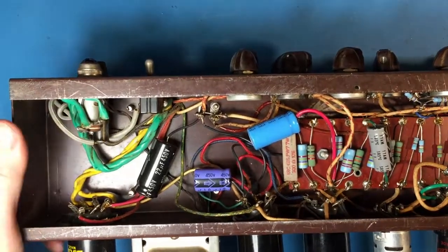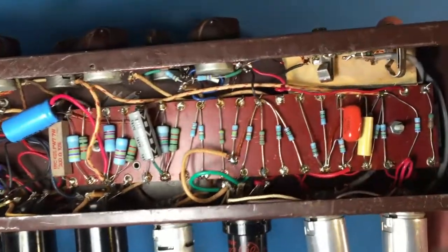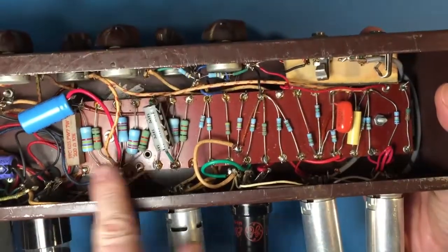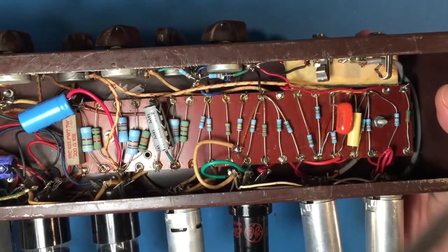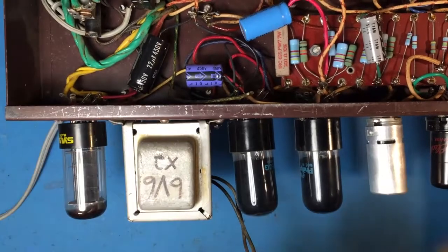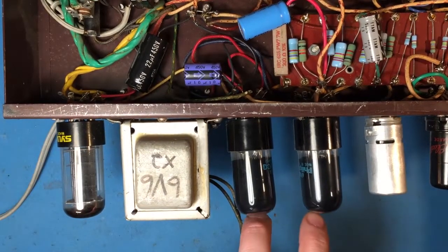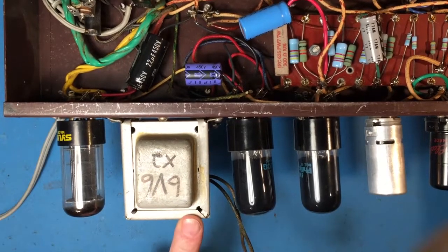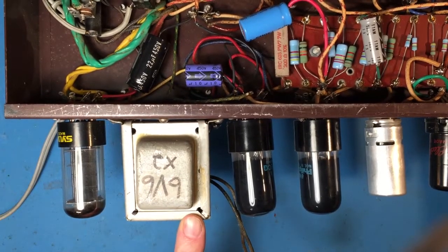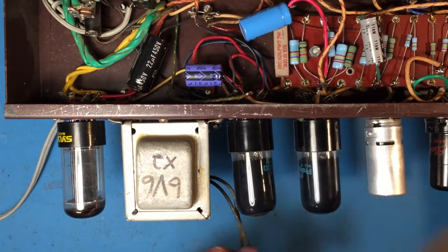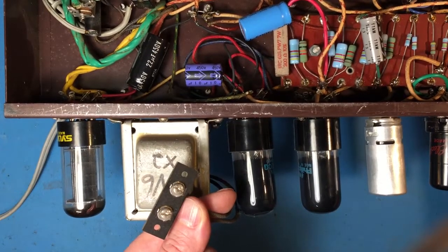Now if we look inside the amplifier, that might be kind of daunting. See all those parts in there? So these are all resistors and capacitors, and those bias the vacuum tubes which are sitting on the back of this right here. And these 2 tubes right here are the power output tubes. Those are doing the amplification, and it goes through this thing right here. This is an audio transformer that basically changes the impedance, the high impedance of the tubes, to be able to drive a low impedance loudspeaker.